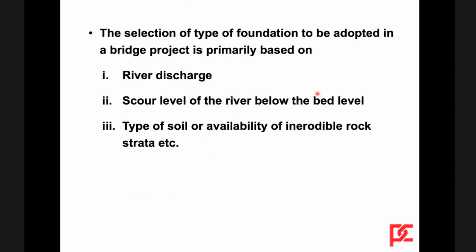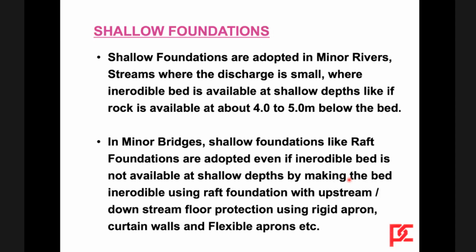Then the selection of the type of foundation to be adopted in a bridge project is primarily based on the discharge, scour level of the river below the bed level, type of soil available, whether inerodable rock strata is available and at what depth, etc. These are the considerations for selecting whether to go for deep foundation or shallow foundation.